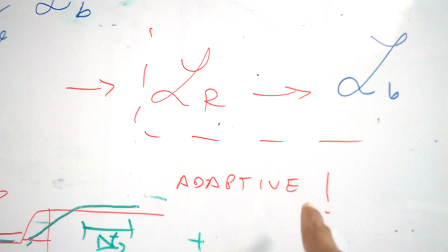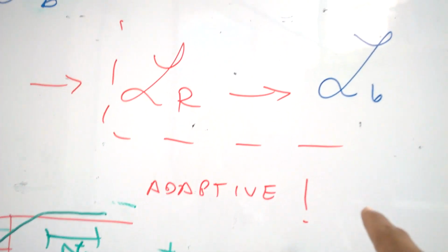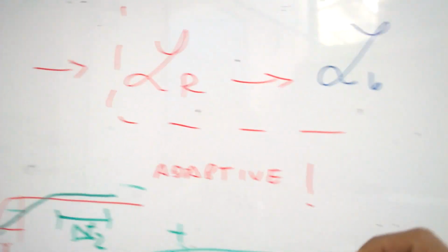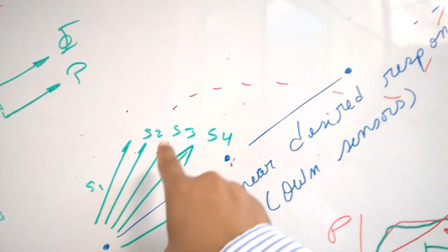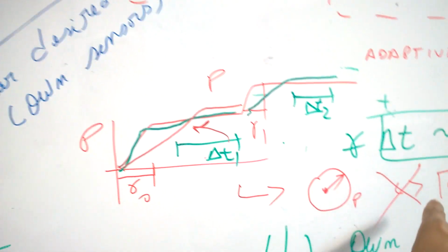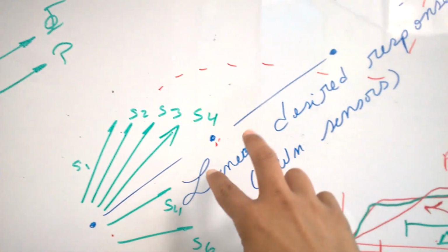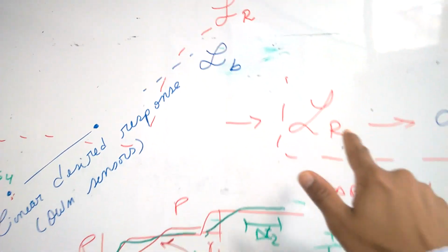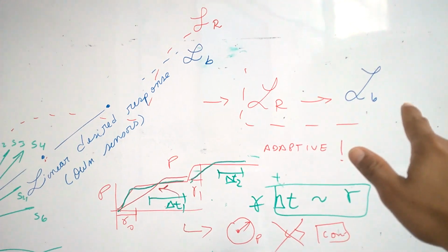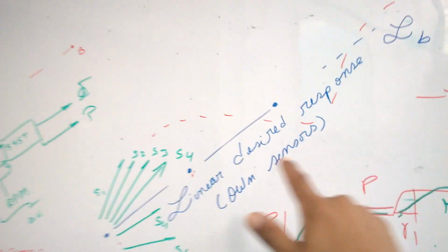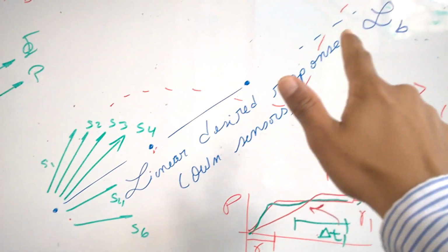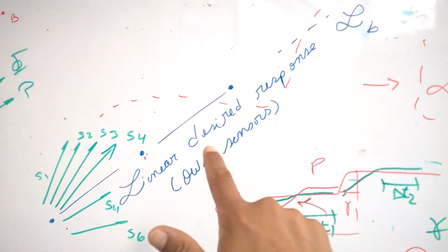The solution is proposed by an adaptive integrated sensor. It implies that by computer we can get an adaptive coefficient so that the sensor will measure this parameter and have its own coefficient in order to adjust this red line to realign it to the blue, or desired, line, which comes from the original sensor's measurement, as it was mechanically measured 30 years ago.